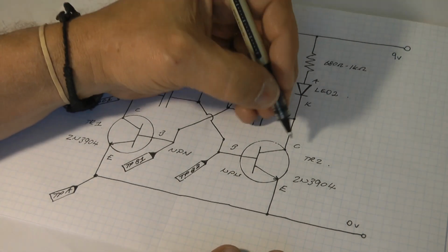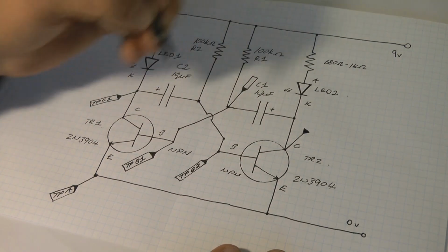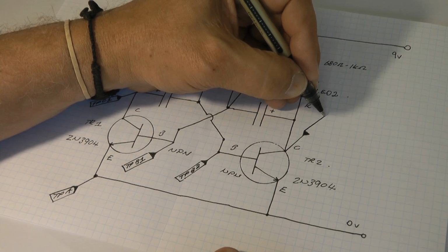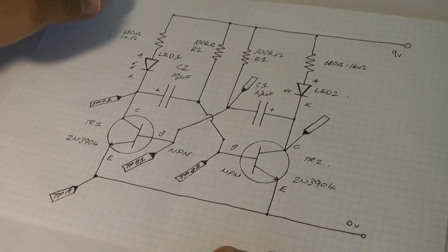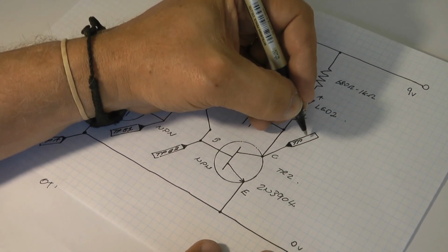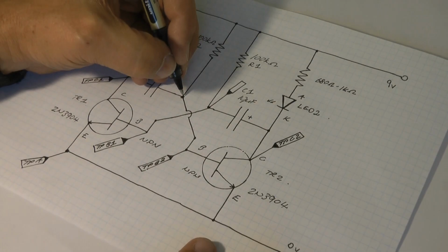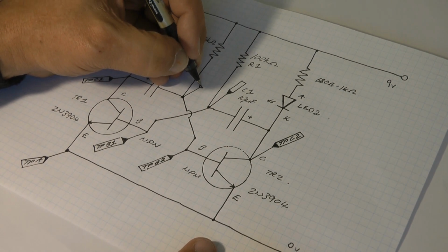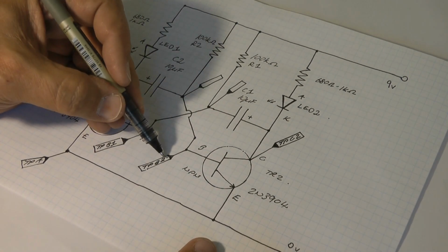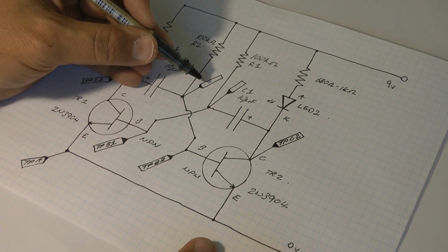Same principle would apply here, where we could attach our multimeter, the red lead, all the while the black lead is connected to 0 volts, because we're just taking voltage readings at various places in the circuit. So this one would be test point C2, because it's the test point on collector of transistor 2. So over here, again, if we were to attach our multimeter over here, it would be the same as attaching our multimeter to test point base 2, because that is connected.